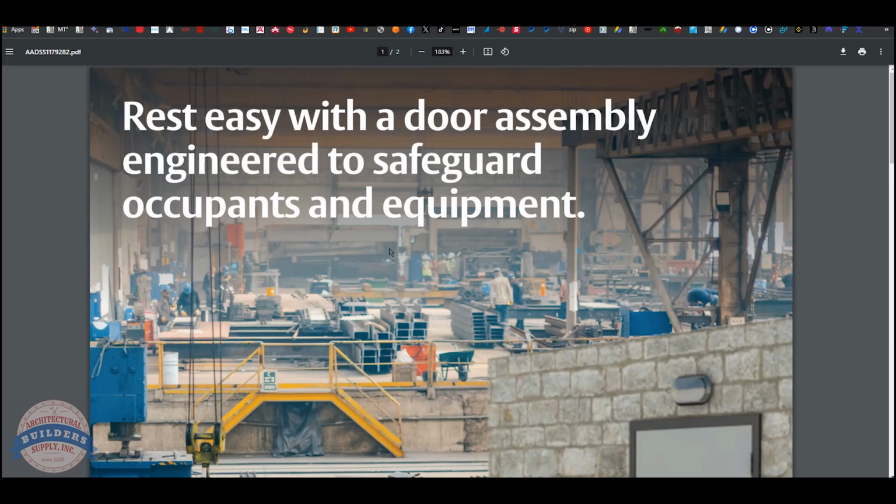Luckily, there's a door company that has the 70 pounds water infiltration not required with half glass exterior doors and a grade 1 lever. So luckily, we don't have to have multi-point locks. Now, let's move to this next point of this video.